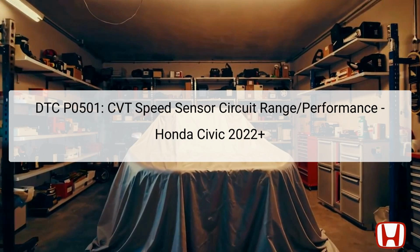When this ratio is out of specified limits, the Transmission Control Module, TCM, registers an abnormality and stores the P0501 code. The correct functioning of the speed sensor is vital, as it directly influences the vehicle's performance and efficiency. Understanding this error is essential for accurate diagnosis and repair in Honda Civic models from 2022 onward.